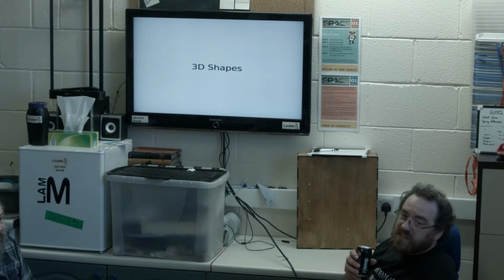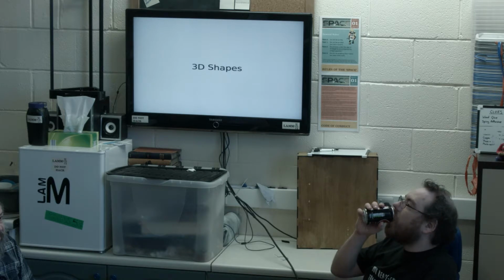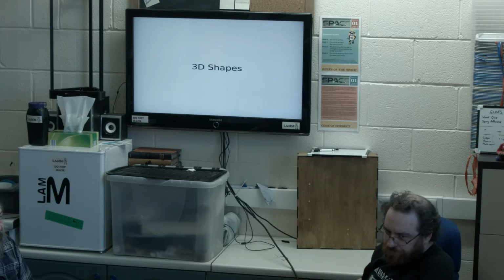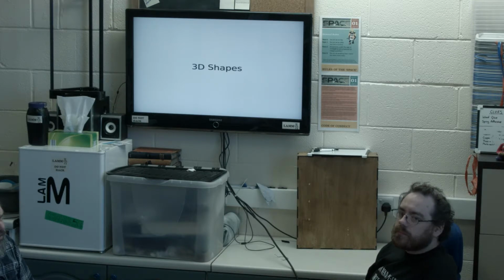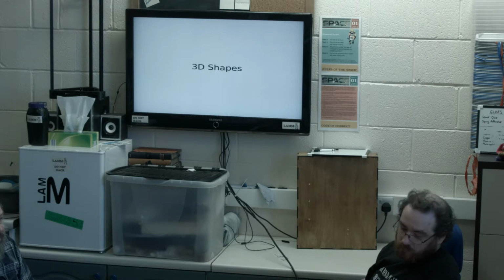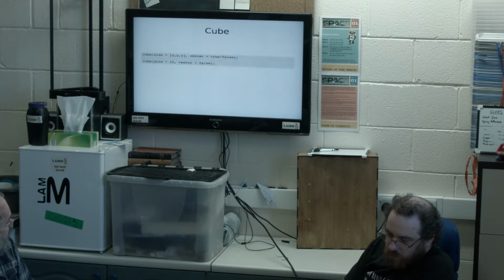One of the things that I like on the OpenSCAD site is that they now have a cheat sheet. That's actually really useful. I went there and clicked on render, and the wikibooks, which is the documentation for render, says: forces the generation of a mesh even in preview mode. Useful when the Boolean operations become too slow to track. Right, yeah. Oh, I see. It's a bit like what I said.